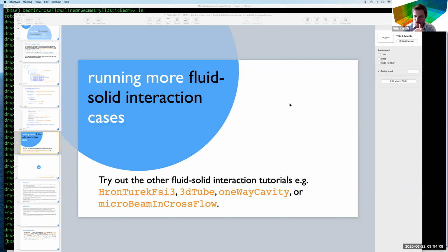If you're using a small strain approach, you don't move the mesh, so you don't have to worry about that. And if you're using a total Lagrangian approach, which is one type of large strain approach, you also don't move the mesh. You just use mathematical mappings at the cell centers. So that's how it's automatically satisfied. When you come to an updated Lagrangian approach, that's where you move the mesh at the end of each time step by interpolating the displacement field to the points. Then, yes, you can add some errors there.